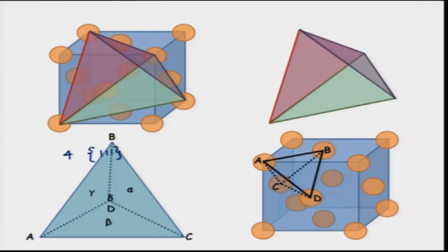So, coming back to our Thomson tetrahedron. So this is the tetrahedron, and like I said, there are 4 triangles and the centers of these triangles are marked by a Greek letter alpha, beta, gamma, delta, and these are located at a unique position. Do not assume that alpha can be anywhere. Alpha will be just opposite to the point we have marked A. Similarly, beta will be marked just opposite to the point we have marked B. Gamma will be just opposite to C, and so on.